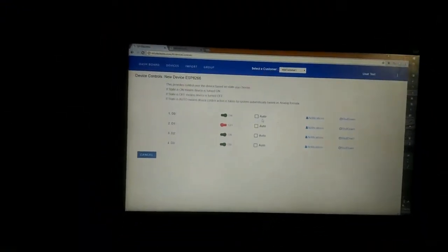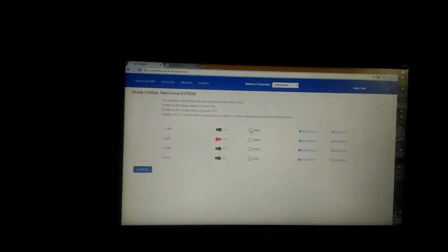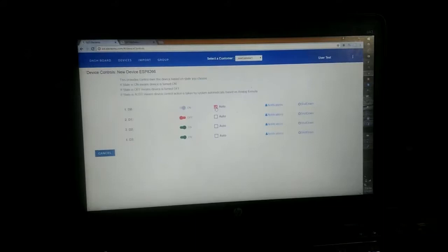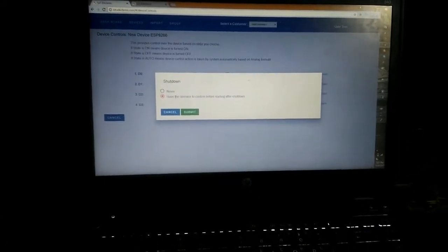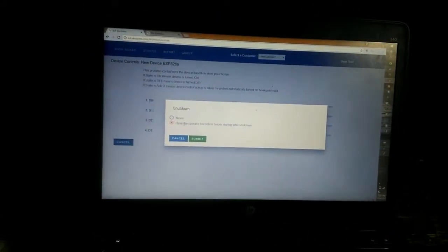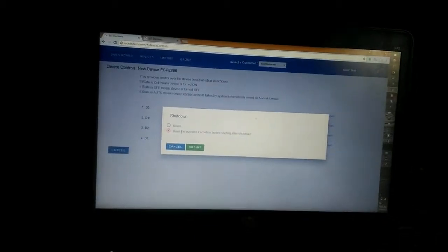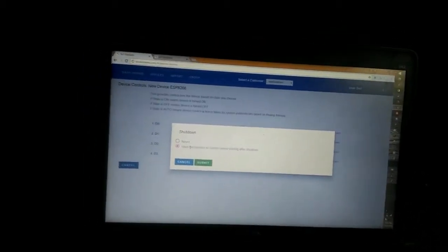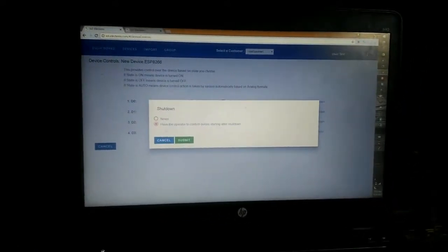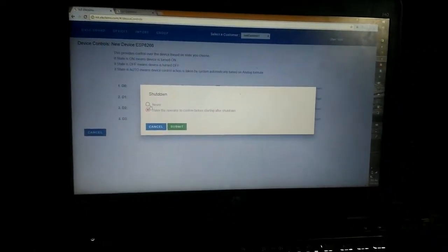Another important feature that you would see is an auto control. In case of auto, we are measuring the analog inputs from the device, which is this, constantly at specific intervals. Now using that, whenever you have a situation wherein the analog inputs match for 4 times or based on your sample size, and with the digital output or the relay output being high or low, these are the 2 options that the system is configured to take.